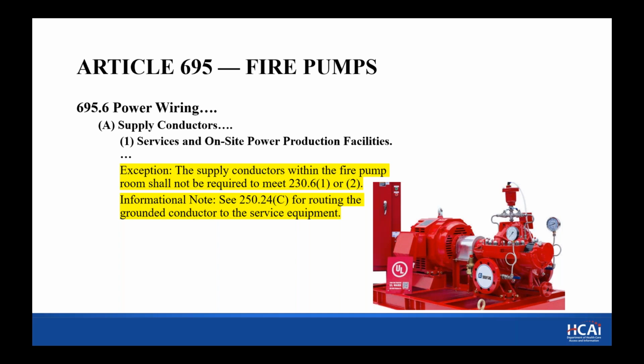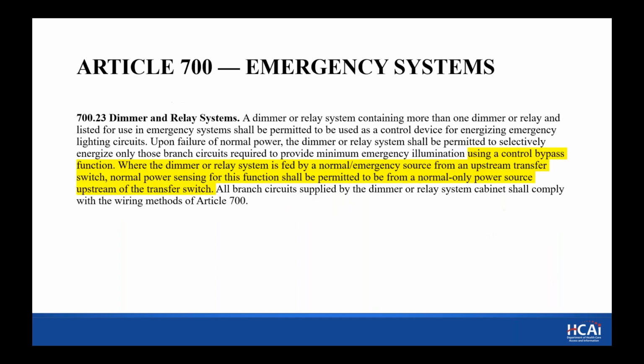Fire pumps. Essentially it gives the exception for the 2-hour protection of the fire pump wiring, so that inside the room, that's a 2-hour rated room that houses a fire pump, that's not a requirement.